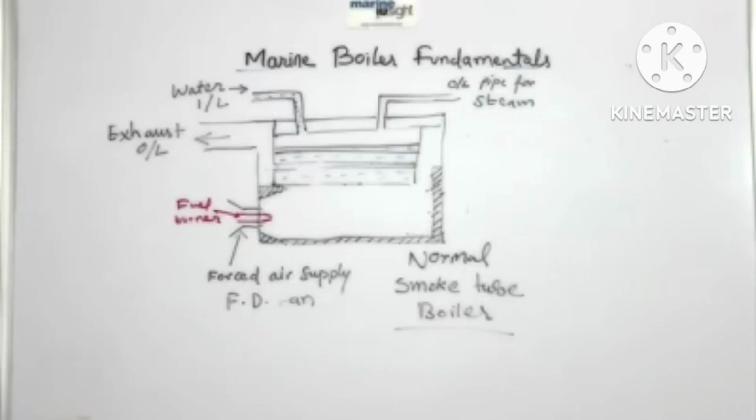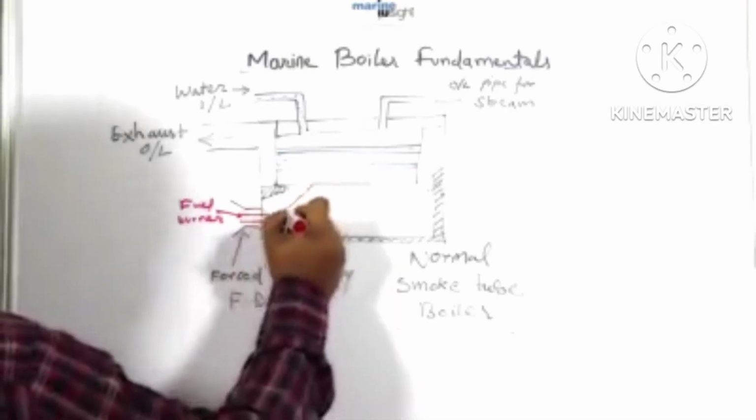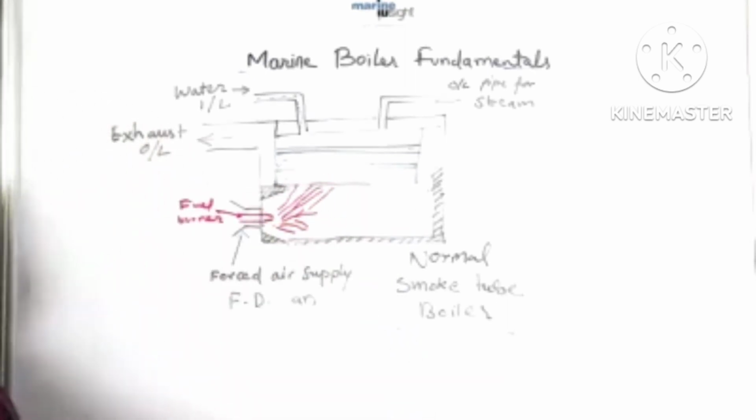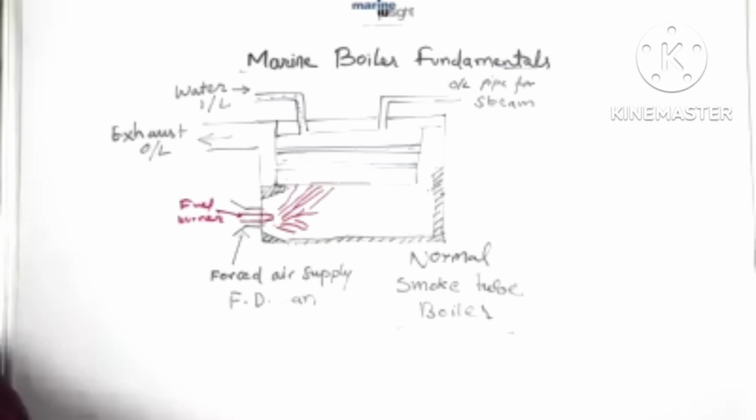Now let's understand how radiation, convection and conduction processes are involved in heating of water inside the boiler. The flame from the burner directly heats the water drum. The water molecules at the bottom part heat up and their density is reduced. This leads to heated molecules rising up and displacing the cold molecules to the bottom part. In this way, the water is heated due to the convection effect.